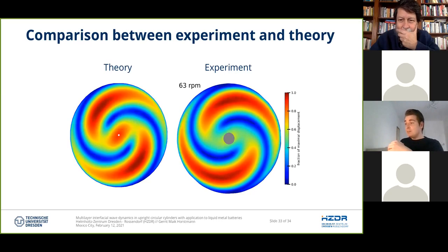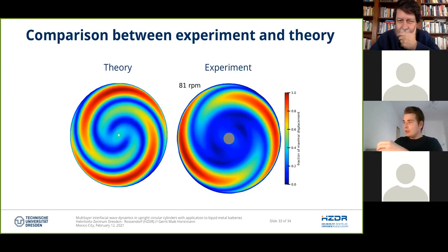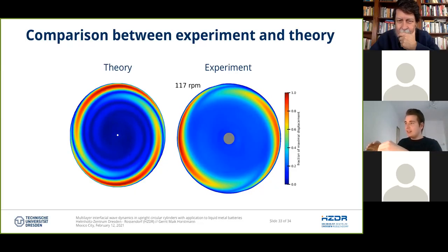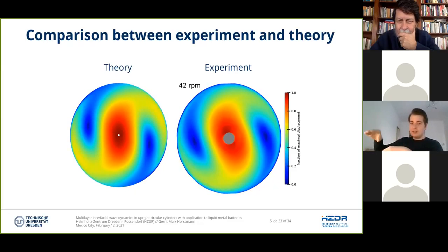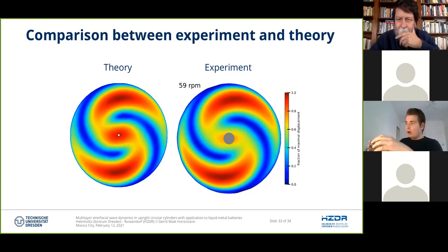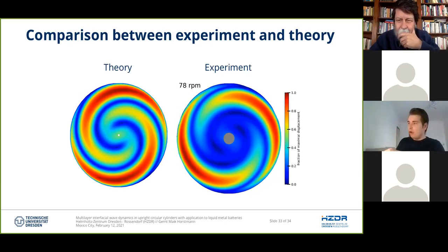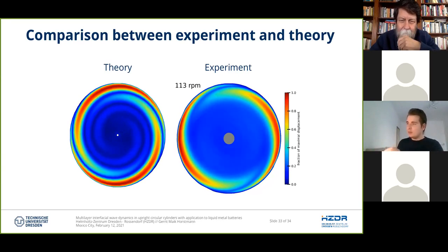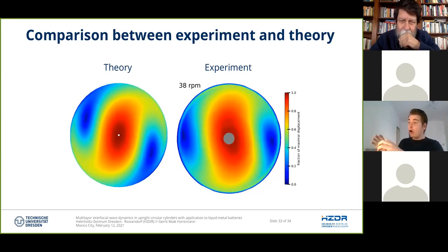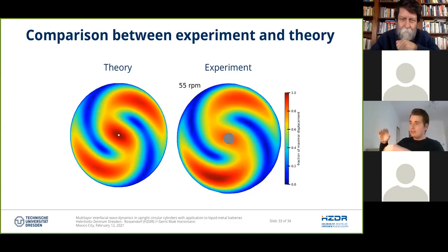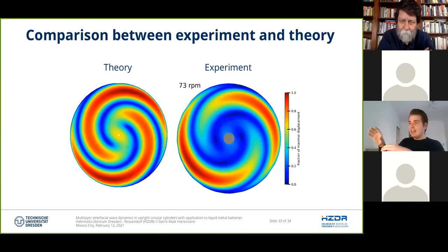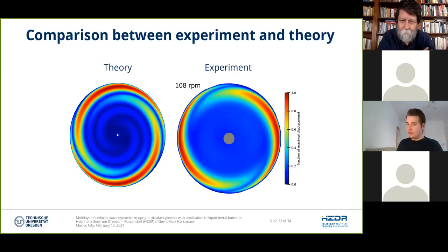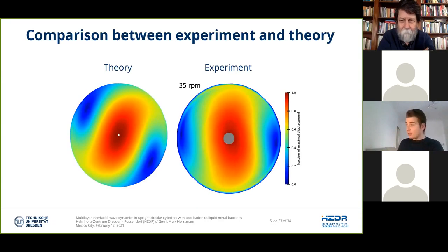I haven't tried it yet because usually these spirals cannot be found, or the reason why they were not discovered before is that in comparable free surface sloshing experiments, water would splash at such high shaking frequencies, for many reasons. One reason is that I have here an order of magnitude slower eigenfrequencies, so I can excite higher wave modes with slow frequencies, not possible with just a one-layer free surface.